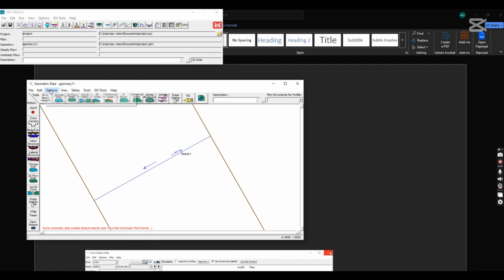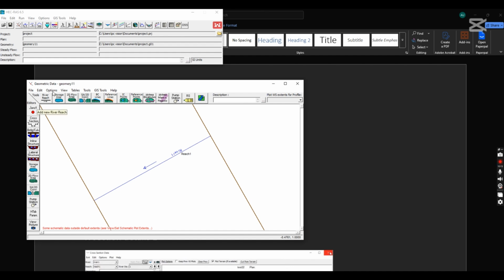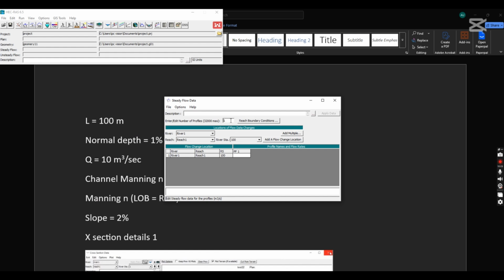Now we will come to the next section, that is basically related to the flow. So now we will insert the flow details. You can close it over here. This is flow detail. If you have 1, if you have 2, if you have return period, definitely you will get here is 1 flow. When you press 2, you can put it over here for this particular section. 2 flow detail, that is return period, 5 return period and 10 return period or whatever you have.